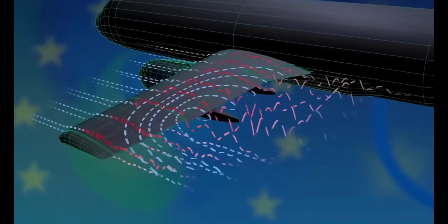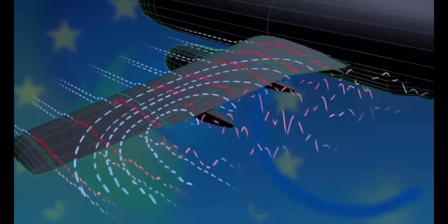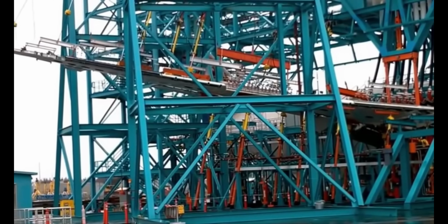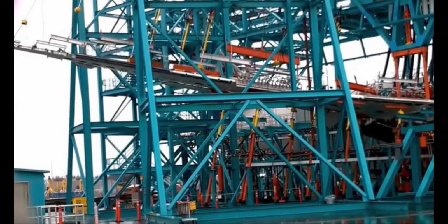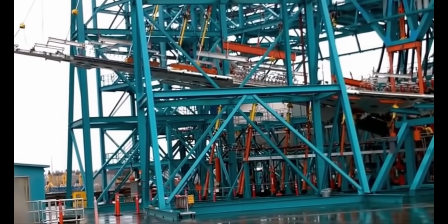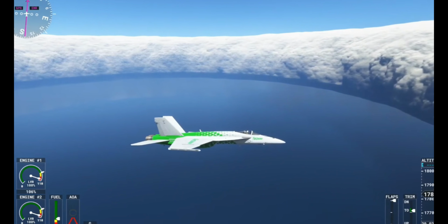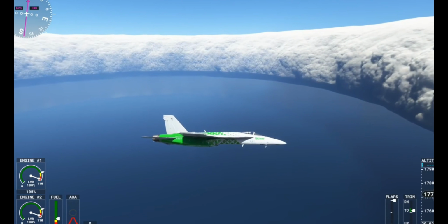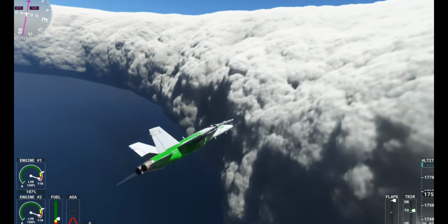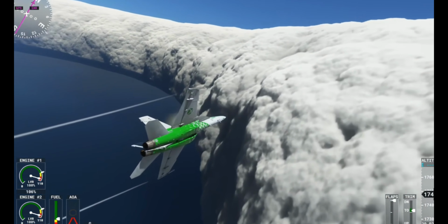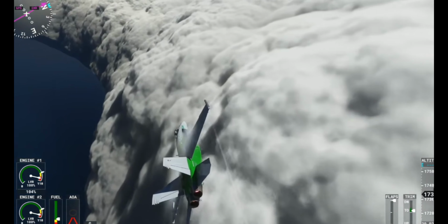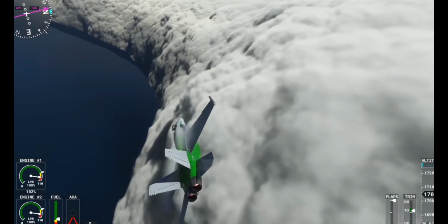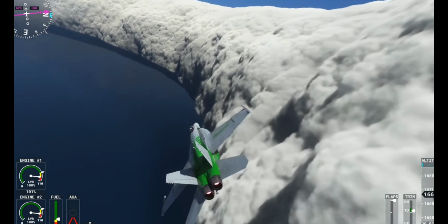Fluid refers to the aerodynamic forces determined by airflow speed and pressure distribution. Structure refers to the wing and fuselage stiffness, mass distribution, and modal characteristics, which determine how they deform and vibrate under load. Interaction means the fluid solver and structural solver exchange information and iterate repeatedly until both sides reach a stable equilibrium. For example, airflow causes the wing to deform, and the deformed wing shape then affects the airflow in return.